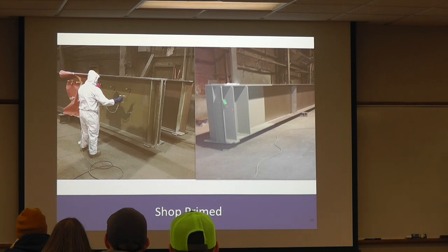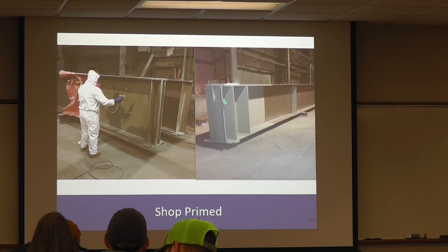This would be just the beam ends themselves, but if it's going to get a full treatment of paint, the entire girder would be shop primed. In Minnesota, we don't do the intermediate or the final coat in the shops, partially because we're doing most of our painting for aesthetic purposes, and it gets so badly damaged by all of the other things that have to happen, right? The deck forming, placing the concrete, removing all of the forming, that it's just not worth it. States out east have had really good luck doing the 3 coats in the shop. So just a little bit of difference in our practices here.